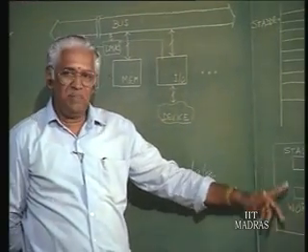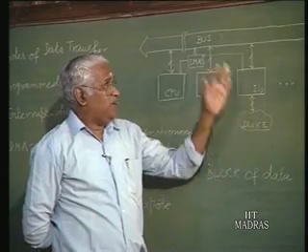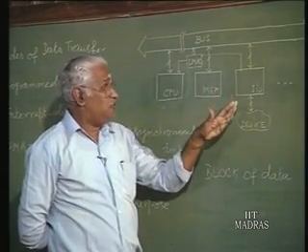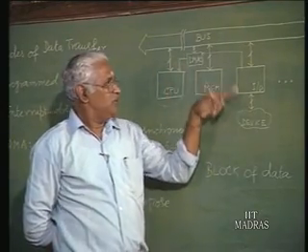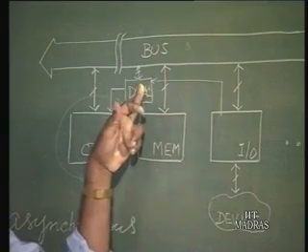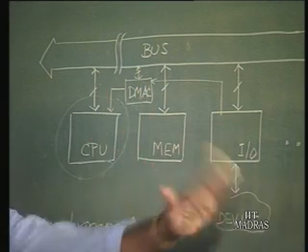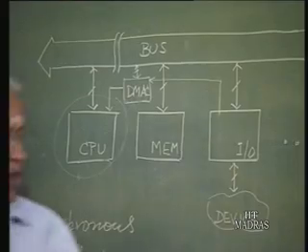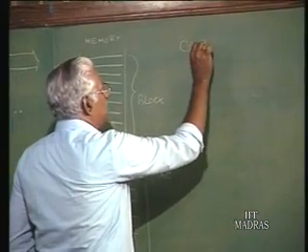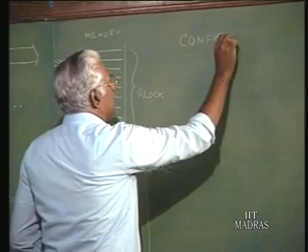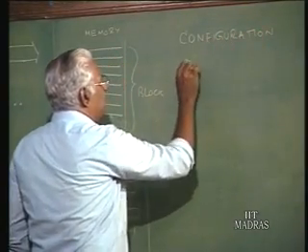These things must have been prepared earlier, meaning well before the DMA transfer can start, even before the device can indicate that it wants a DMA transfer through this request. So, if you recall, I was earlier talking about 2 phases, one called the chip configuration phase, and another one the data transfer phase.